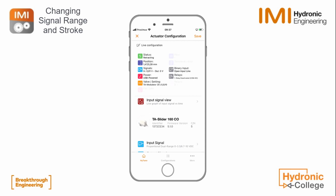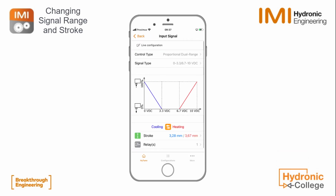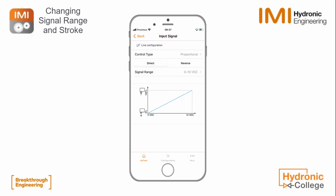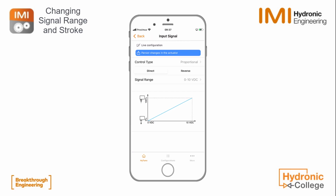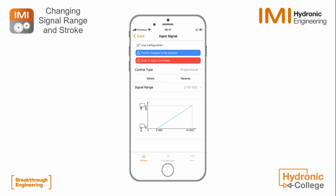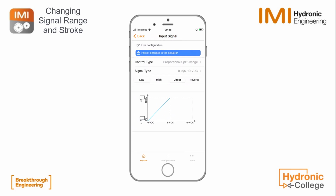By clicking on input signal, we can see the current settings or change the settings into the desired ones. So we click on input signal, and then you see now we're in dual range. You will see in control type 3 options, and we'll take proportional first. So then you can set direct or reverse, or change the signal range from 0 to 10 volts, or to 2 to 10 volts DC. Now you see there is an error as we are only having 0 volts as an input for the moment.